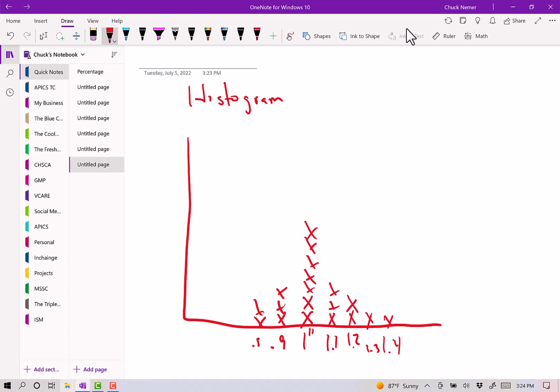So what we can get out of it is something like this that says, hey, it looks like a normal distribution. The bell curve and a normal distribution means it's a process that's under control and behaving normally with no outside influences. But it can also tell us this, is we may take a sample that looks like this. And we go, ooh, it looks like half of a normal distribution. How's that possible? And normally it shouldn't be. We should expect to see the other half of the normal distribution.